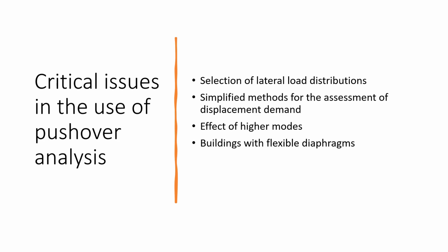But again, we are dealing with simplified methods to compute the dynamic displacement demand, because we are not performing a dynamic analysis. We use a simplified rule comparing the ductility of the system, the ductility requested for an equivalent single degree of freedom structure.